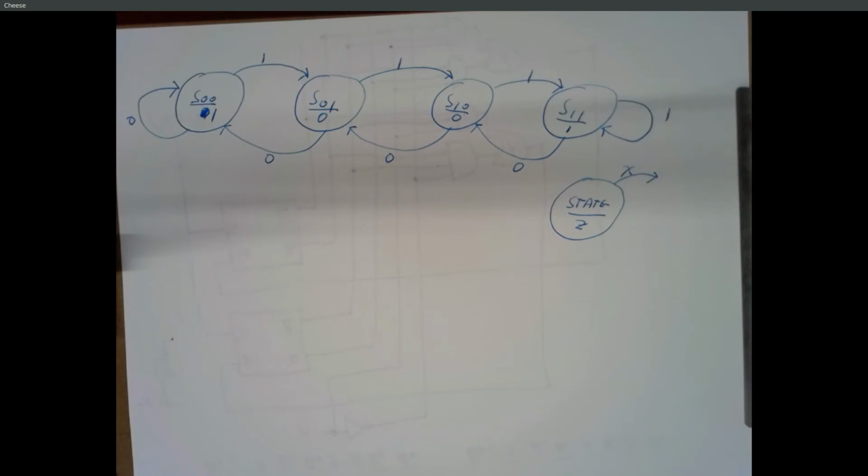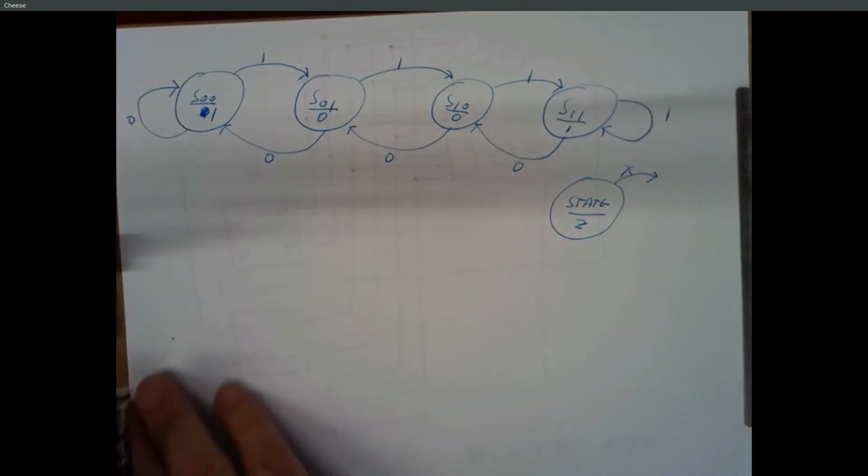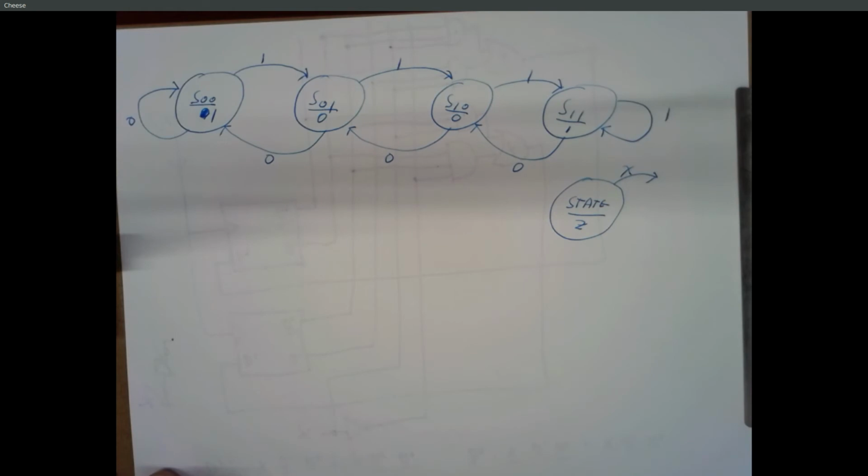All right, excellent. So we don't need to know what the machine is doing. All we need is a state diagram, right? But sometimes it's useful to think about what it's actually doing. But it's not a necessary step. All right, so 4 states, how many flip-flops should we use? Let's use 2 flip-flops. If we use 4 flip-flops, that's 16 rows times 2 for our input. That's going to be 32 rows in our state diagram. But most of them are going to be don't cares. And it's actually going to end up being easier to implement the circuitry, usually. But it's a big table. So let's do 2 flip-flops.